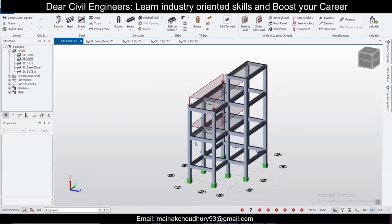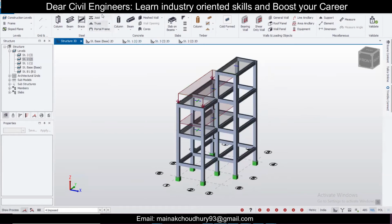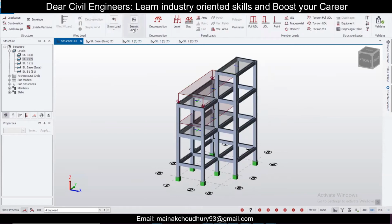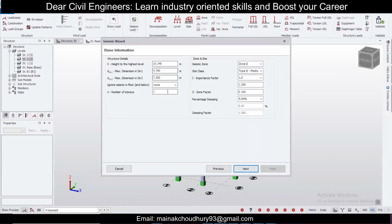In any code, if you're in a high earthquake prone area, then you need to provide it. Let's see how to provide the earthquake load. Go to load here, and here you have an automatic option of seismic wizard. Then select code spectra that's recommended, and then just select the seismic zone.